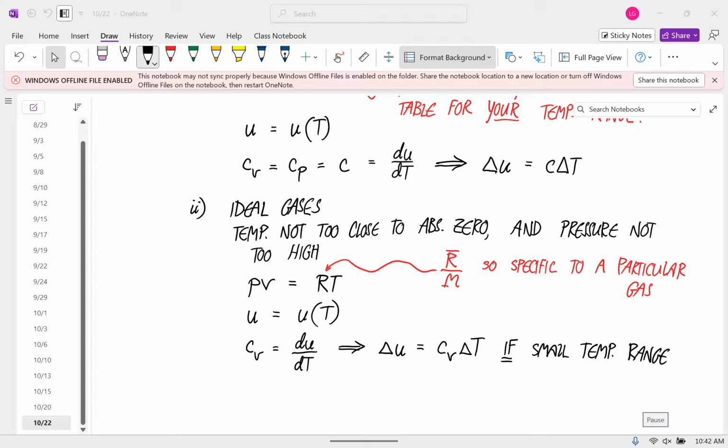It just basically has to do with the shape of that specific heat if you graph it versus temperature. For a liquid, the specific heat is pretty constant as the temperature changes. For a gas, if you graph CV versus temperature, you get a pretty major nonlinear shape. And so this only works for pretty small parts of that graph. I mentioned before, we haven't done it this way in this class, but you might think, that's the problem, is that CV varies a lot as temperature varies.